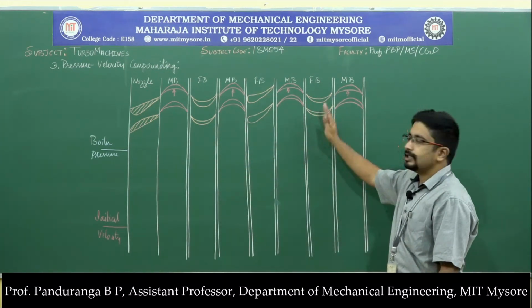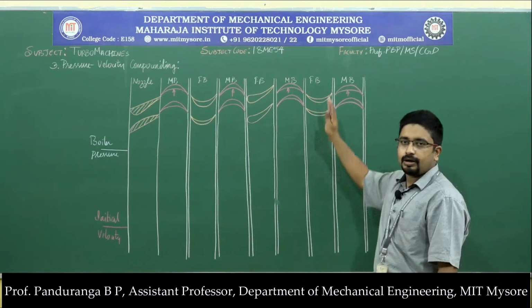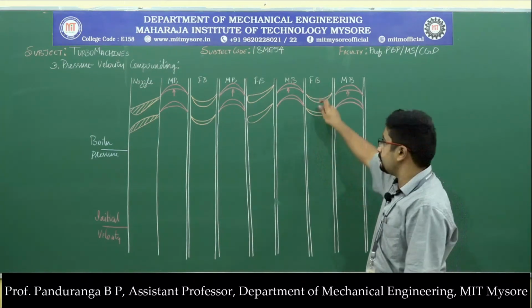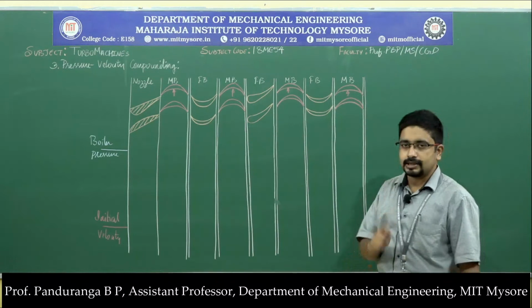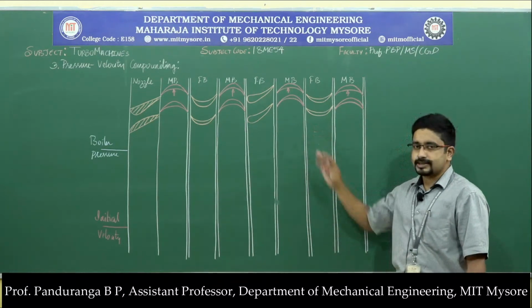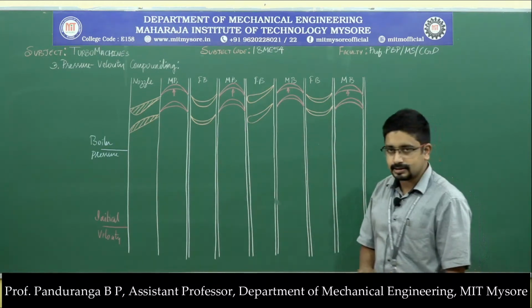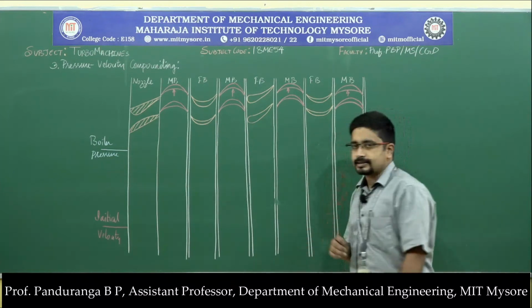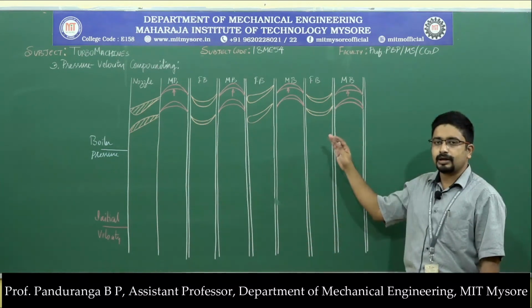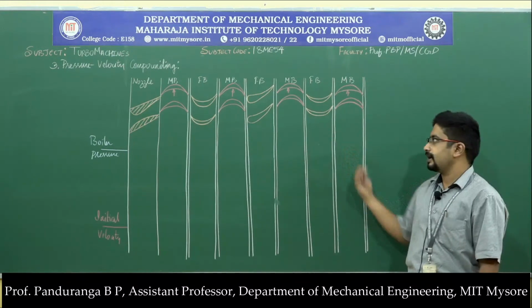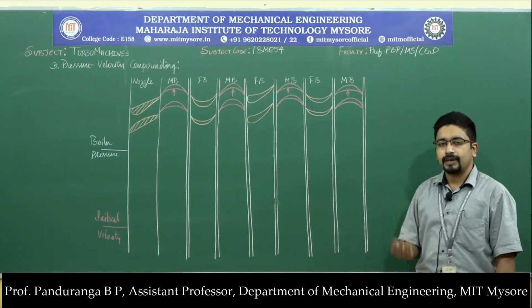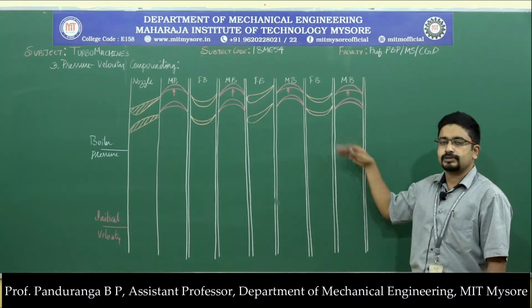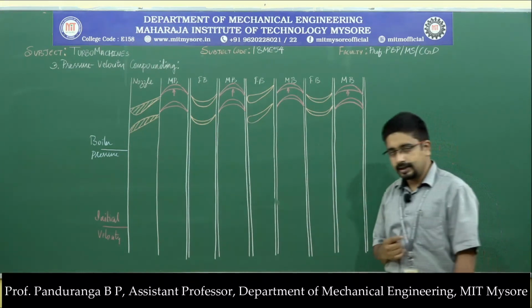and because of that there is no change in pressure or kinetic energy. Since the flow area remains same, pressure energy remains same. Since the blade is fixed, kinetic energy remains same. And then the steam enters the last stage, where the kinetic energy of the steam will be converted into mechanical energy, or the kinetic energy will be absorbed by the moving blades.